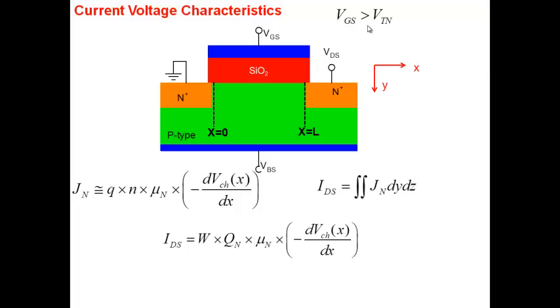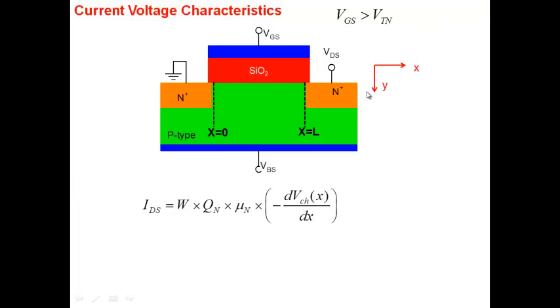All right, so we are talking about, of course, VGS larger than VTN. A channel has been formed. And so one of the first assumptions that we are making, we will try and keep track of the assumptions that we keep making in order to derive. The first assumption is that current is primarily drift. There has to be a diffusion component, but we are saying it's negligible, which is a good assumption as long as you are above threshold. The moment you go below threshold, you find the diffusion component becomes important. If time permits, we will see that. Okay, so this is the expression for current here.